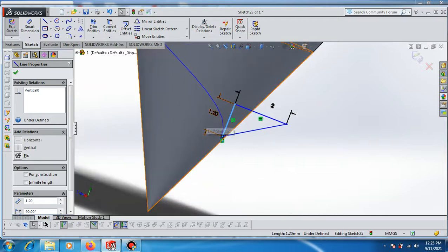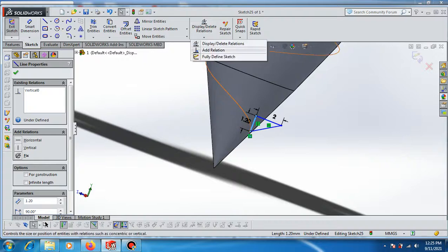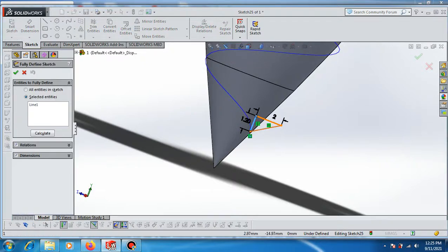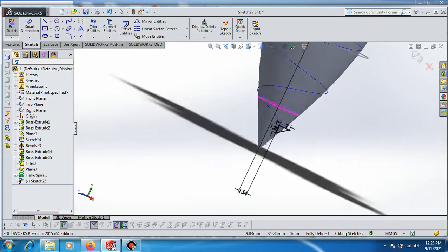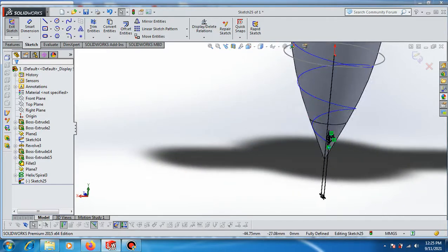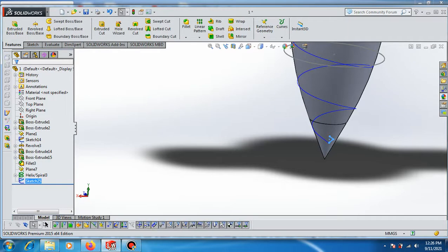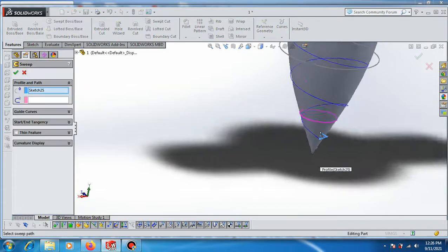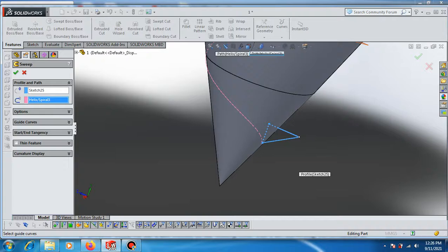Okay, but for us to fully define the sketch, check. So we just go to the origin, and then next thing to do is Features, then exit sketch, then go to Features, sweep, then choose the object. Of course this object is that one, then what particular sweep, this one, and accept it.